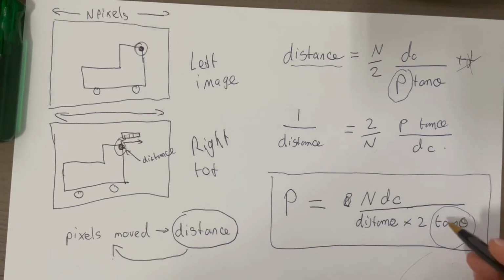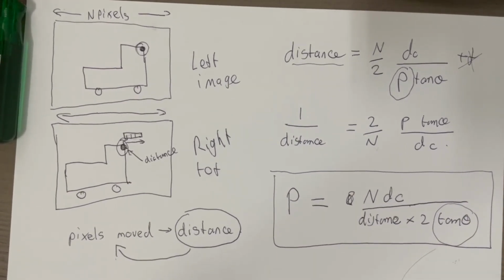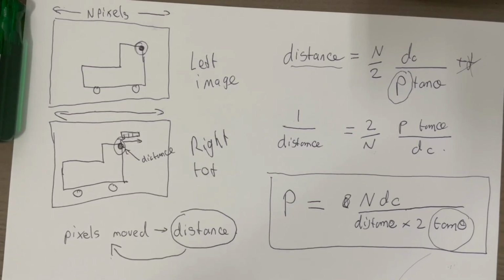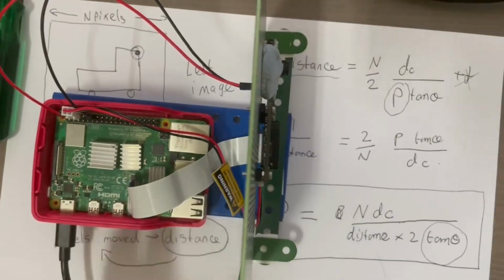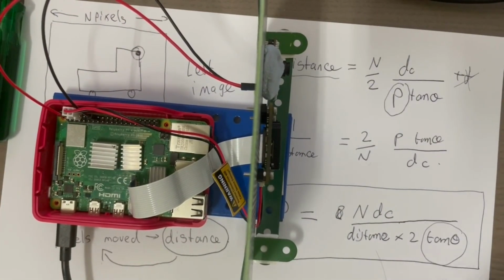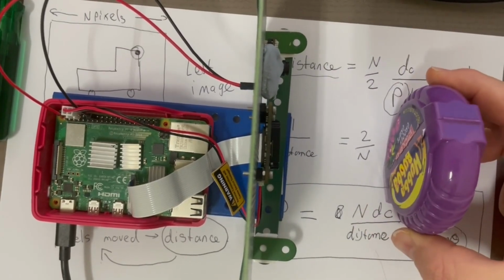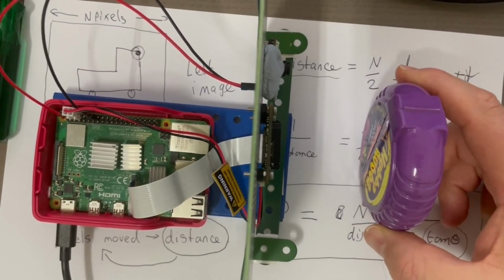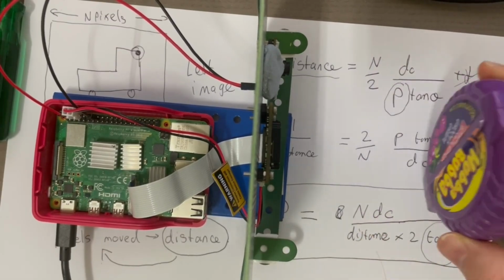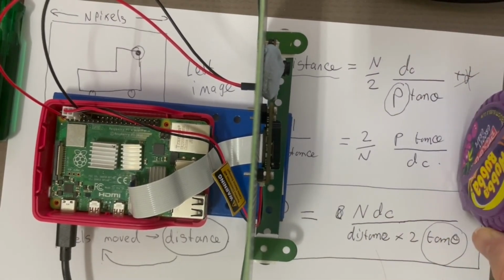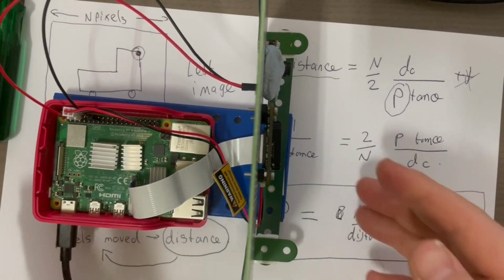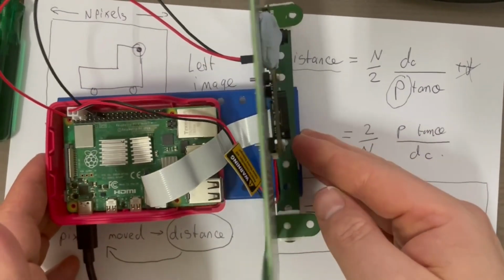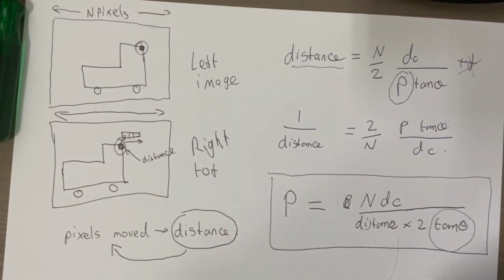So what I had to do was fudge this so it kind of matched. But a better way to do this would be, I guess, a manual calibration. So we take the camera, and then we put an object, say, 10 centimeters away. That's not 10 centimeters, but I'm not doing this to scale. And then we move it 20 centimeters, 30 centimeters, 40 centimeters. And at each measurement, we see how far we have to move the time of flight image.